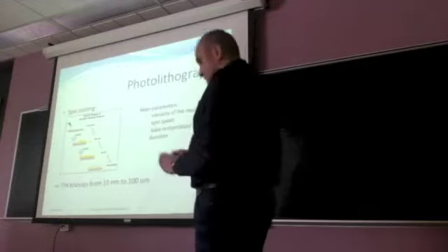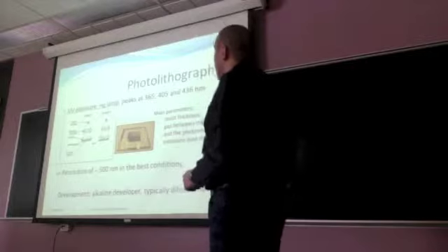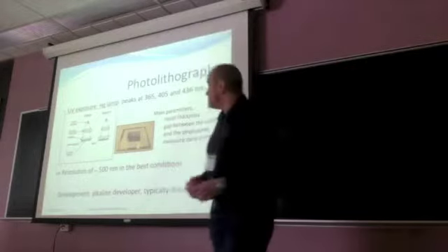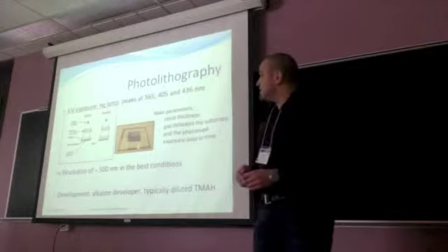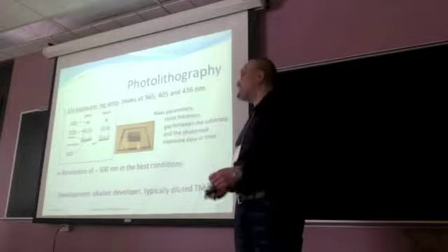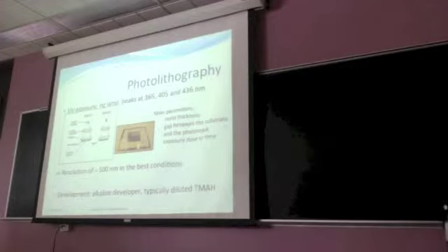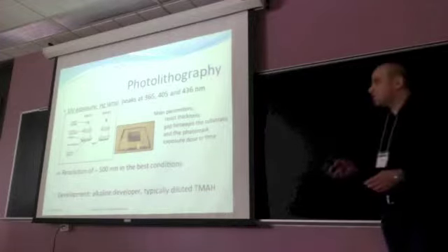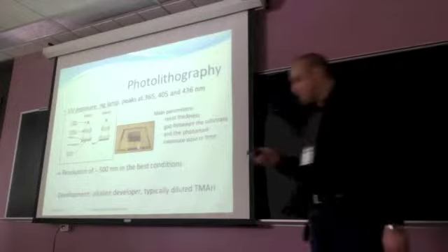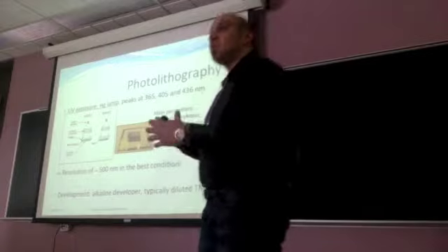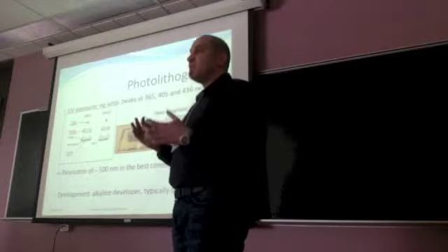So the second step of photolithography is UV exposure. The source of UV is a mercury lamp with different peaks. And UV radiation is uniformly distributed over the wafer through a photomask. And here you can see an example of a photomask. A photomask is a glass plate with chromium patterns which block light. And I have 2 examples here.